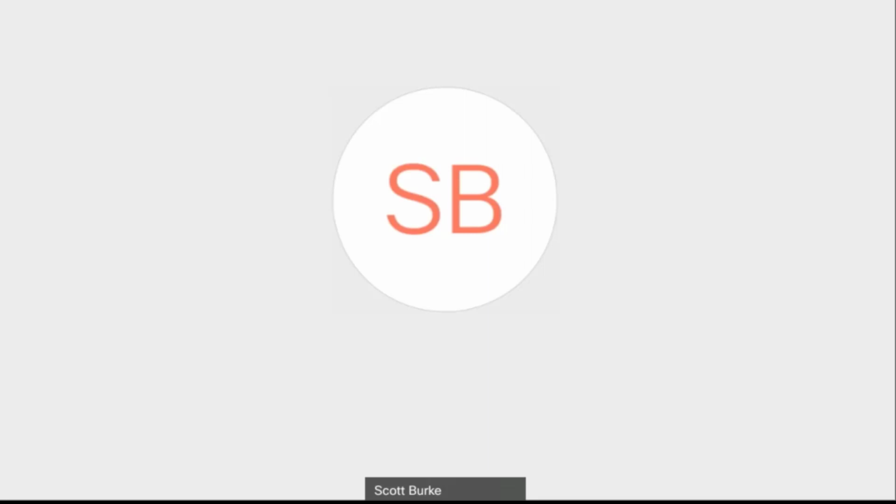Another question here, we have projects in 2017 and 2019. Do they need to move the 2017 projects to Revit 2019 prior to using the BIM service? Normally, the answer might have been no, but I believe with the trial, the team site, the old collaboration for Revit, is not included. So in this case, yes, you cannot use 2017 in the free trial. If you have a paid site, then you could actually use 2017. But otherwise, you'll have to upgrade everything to at least 2018.3 and above in order to use the new BIM 360 Design site. That's important there.